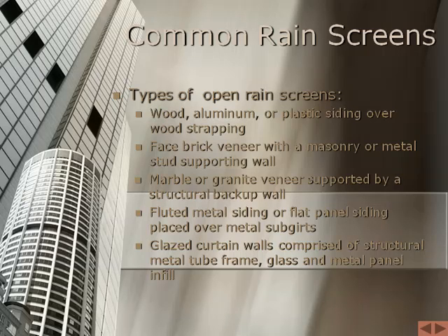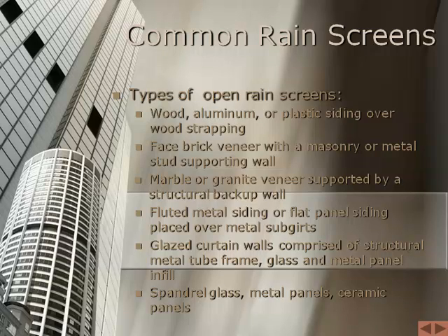More recent examples of rain screens include an outer cladding of spandrel glass, metal panels, and specially manufactured colored ceramic panels. Masonry cavity walls are an application of the rain screen concept and are used extensively in Europe and North America, where they have been developed as a means of obtaining protection from penetration of rain through walls. In recent years in North America, many significant buildings with differing cladding types have been constructed with cavity rain screen walls.